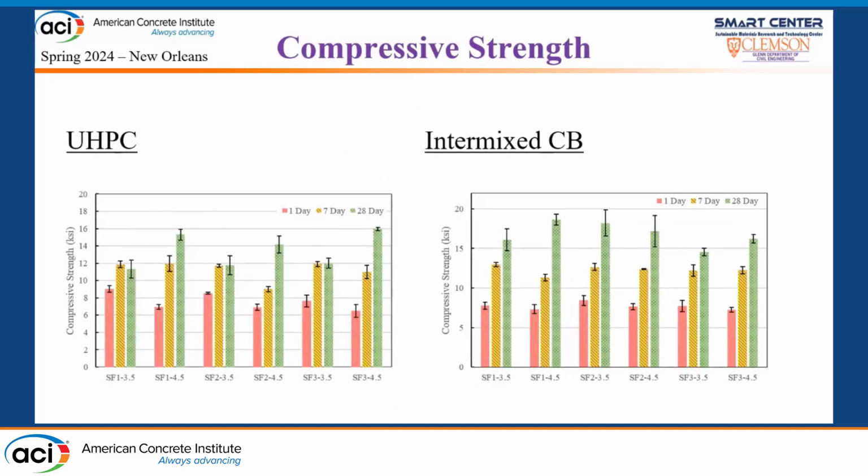Next, and this is the part that's kind of weird for this work, is the sacrifice we made in compressive strength. Because we were using more available materials that had less inherent compressive strength than siliceous-based sands, we were seeing for our pure UHPC mixes, compressive strengths between 12 and 16 KSI, which is below most UHPC specs, especially ACI's at 21,000 PSI.